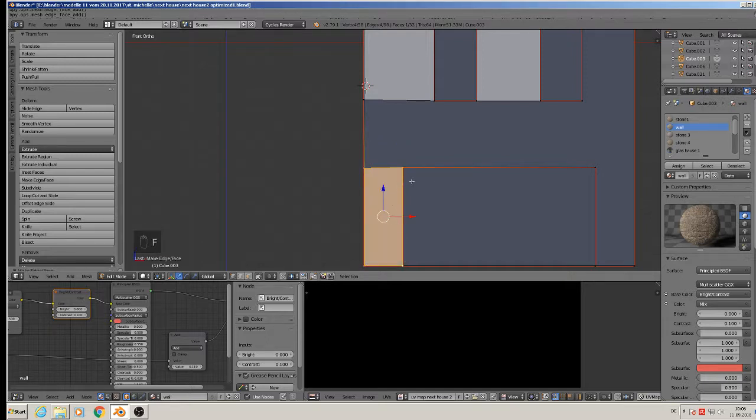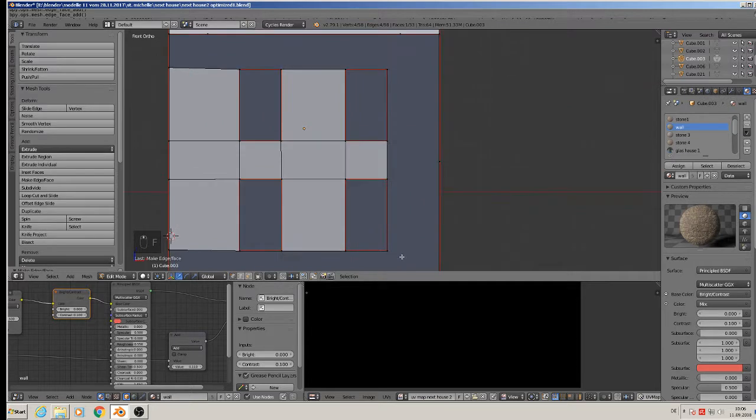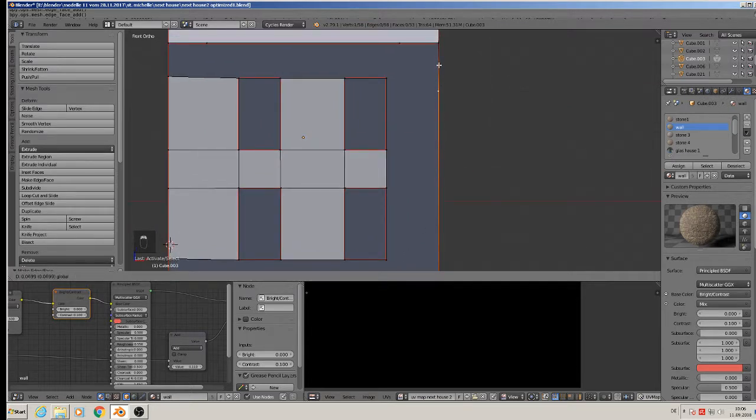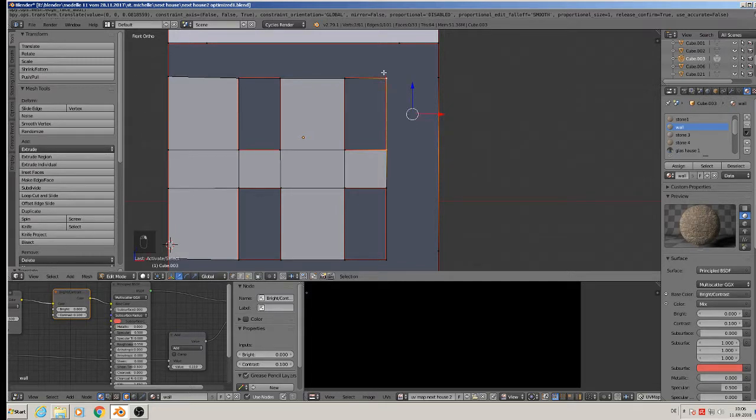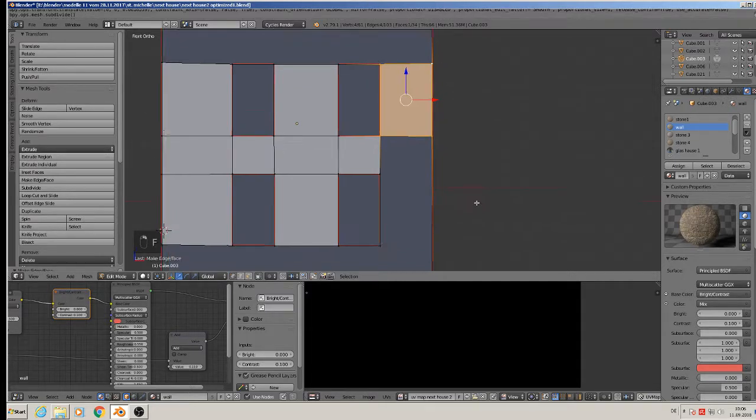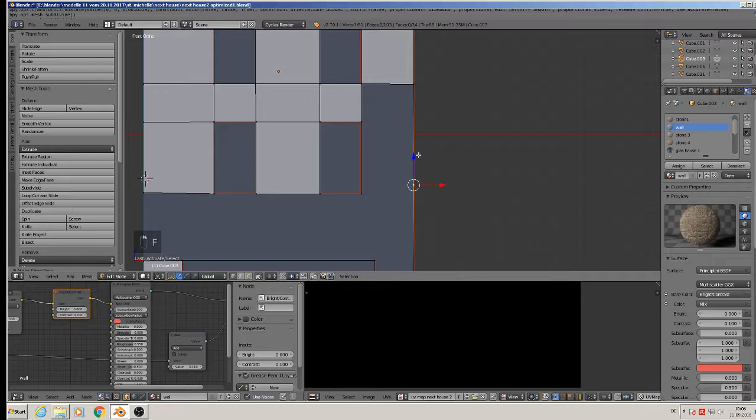But we see when we want to close there, we normally need there one, but we will see. F to close that. Now we have to do here the same as on the other side, so we place one there. Then we take here the edge and subdivide 2 times. Get here back to vertex selection, go here higher and close this face. Then we bring up them here and close this face.